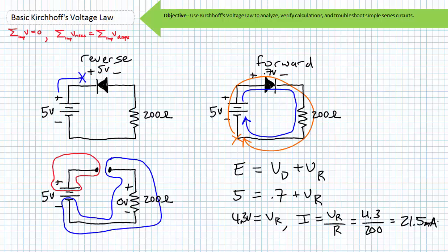Too easy. Even though we're using devices typically reserved for discussion in second-year electronics engineering technician classes, we're still already capable of solving these types of problems using basic electronic principles like KVL. Keep in mind the diode comes in all types of flavors, including silicon, germanium, and light-emitting varieties. Don't assume this 0.7 volt drop when in the forward bias mode is universal.